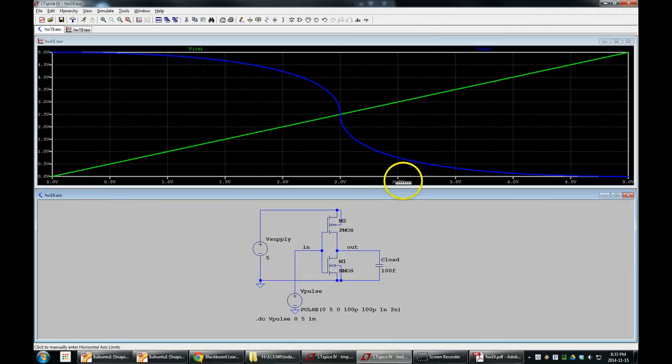What we want to do is find VL and VH. Those are the easy ones. VL, the output low voltage, goes all the way to 0 volts. It turns out you can measure it, but we're going to round it to 0. The output voltage here goes all the way up to 5, so VL and VH are 0 and 5. Those are really the easy ones for this CMOS stuff. The hard ones to do are VIL and VIH. An input low is considered anything from VL to VIL, and VIL is where the slope of the output is -1.